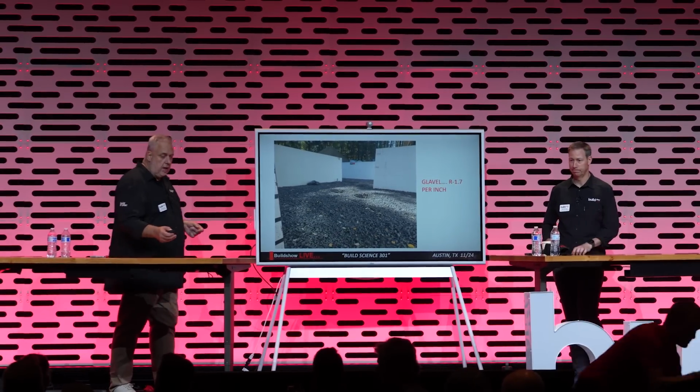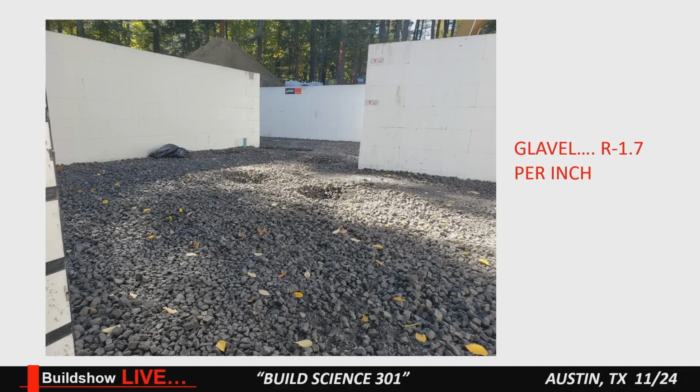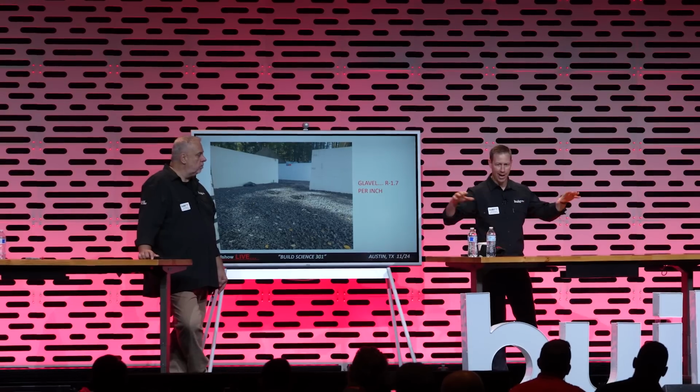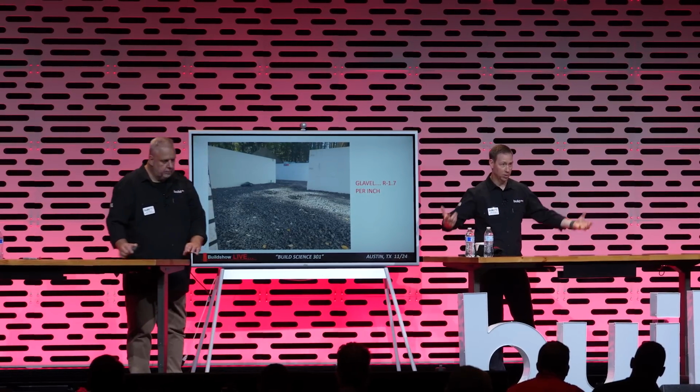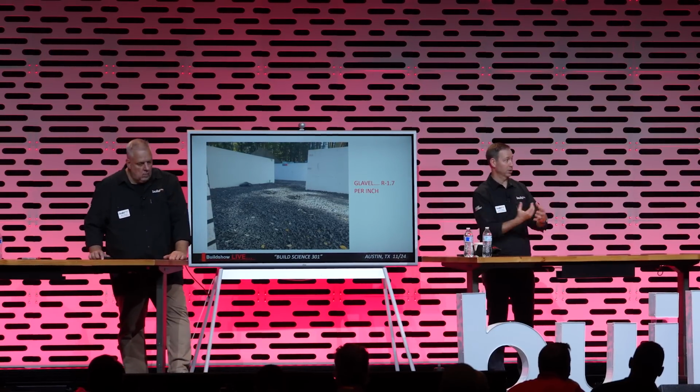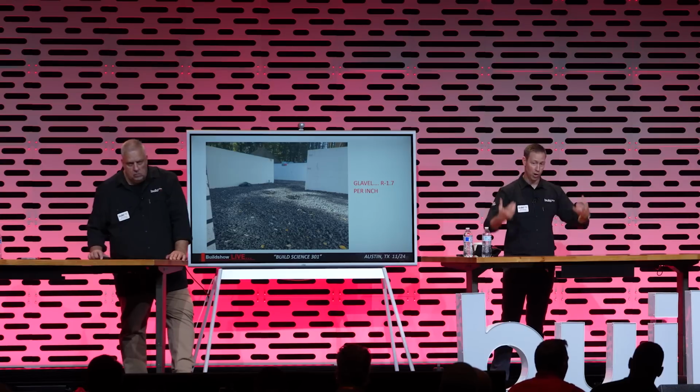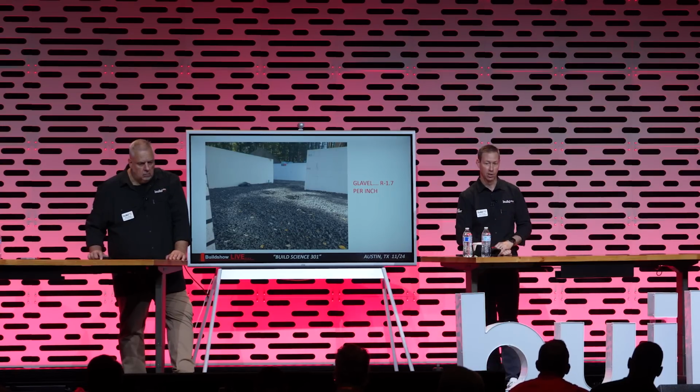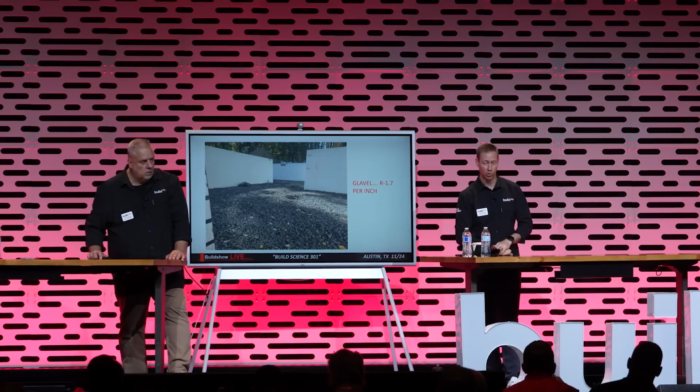Good backfill medium. Yeah. It feels like a real light, like a lava rock or a charcoal briquette. Super weirdly lightweight. And as you stack it, it's got good drainage, right? Because it's big rocks, not small dust. So water, if it got in there, would easily be able to drain. And especially important on a site like this that's real close to a river.